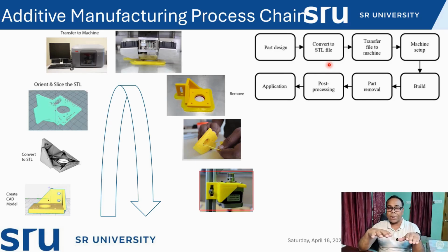So what will happen in the slicing operation, the path can be generated, that path having details like X coordinate, Y coordinate, similarly the G code or M code, meaning how it will be rotated clockwise or anti-clockwise. So all details, G code, M code, X coordinate, Y coordinate for each layer will be generated, as well as the entire profile of each layer.